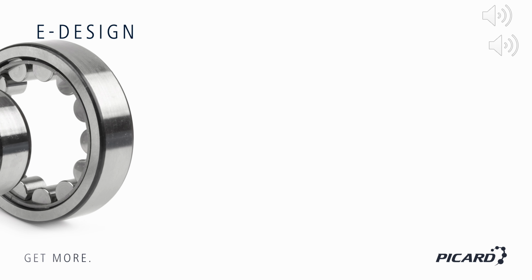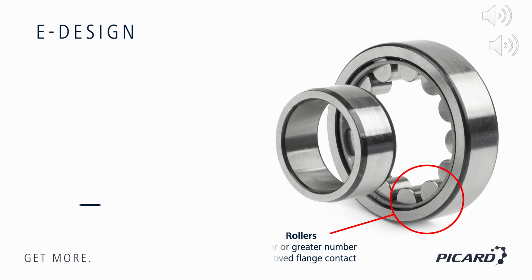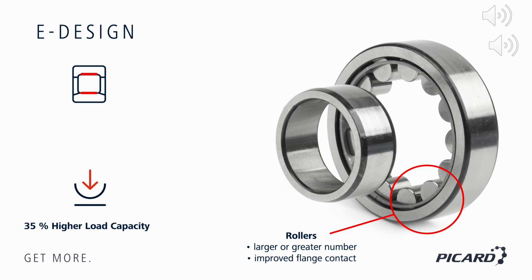In the 1960s, the so-called E-bearings were developed. Due to a higher number of rollers, they provide an average increase in load capacity of about 35%. The letter E stands for a reinforced and optimized internal design, for example, through more or larger rollers and improved contact conditions between the rollers and the flanges.